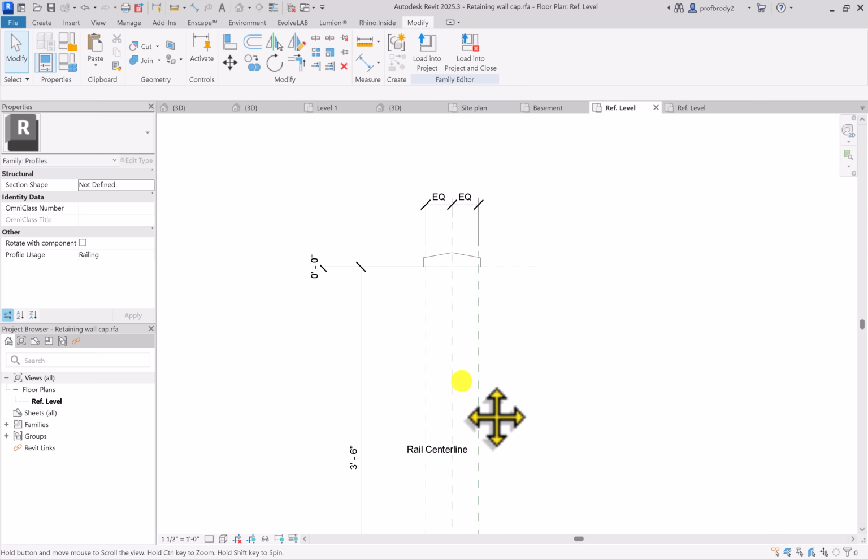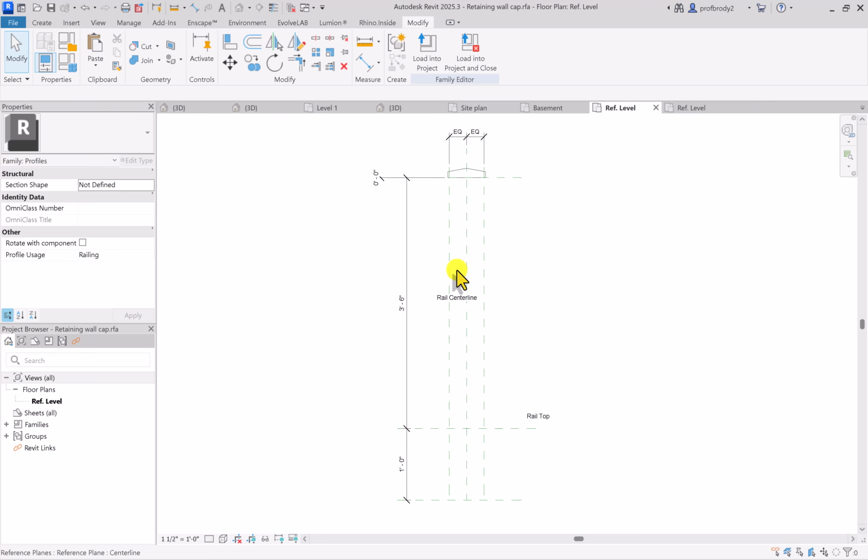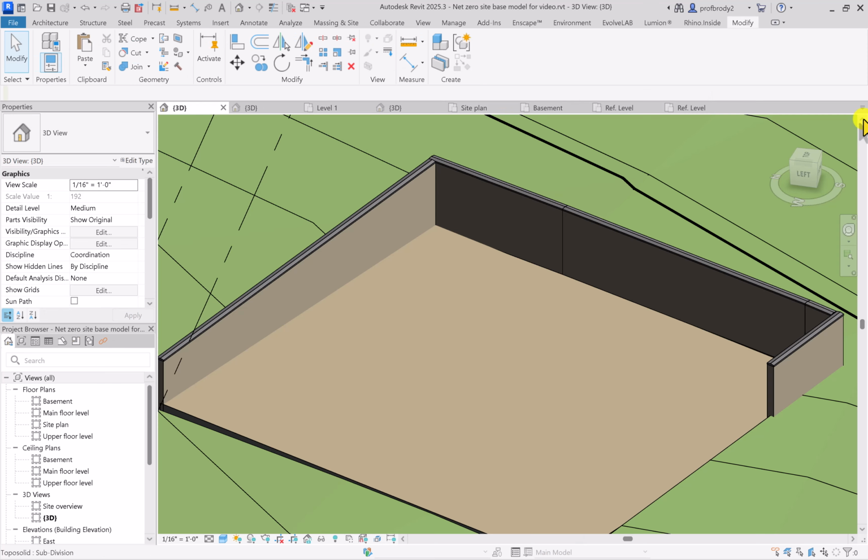And then I actually created a little parapet kind of cap to this thing that's set. I just copied the family to have this one show up right at the top of the wall. And this technique is terrific for those walls you want to follow along. And of course you can do chain link fence or other sorts of things. You can almost certainly find railing families down on the good old internet where you can get all sorts of different things. And so absolutely you can customize your site constructed walls quite easily using railings.